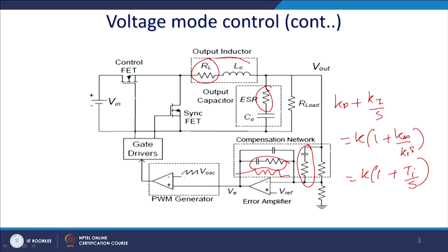If there is a very huge load drawn, it only tries to regulate the voltage, and it does not take any information about the current. For this reason we require to put extra circuitry to limit the current for protection.